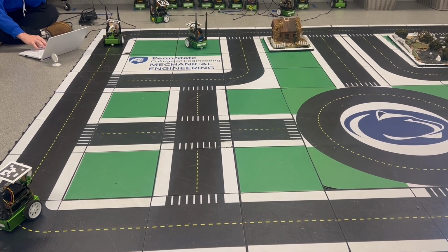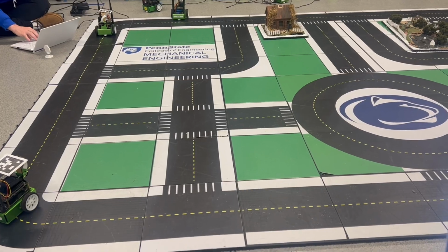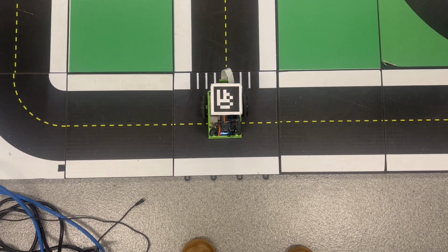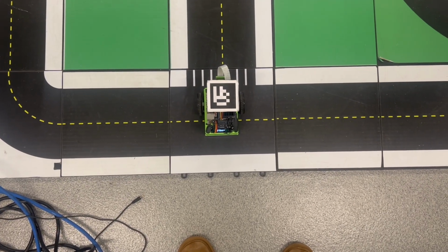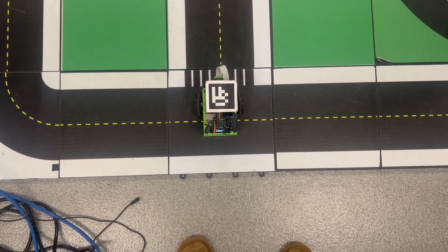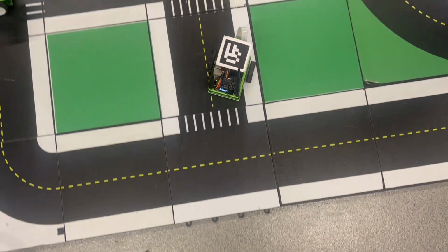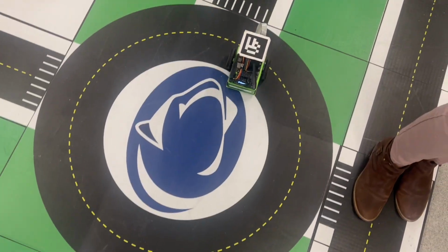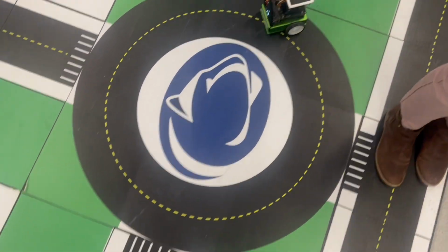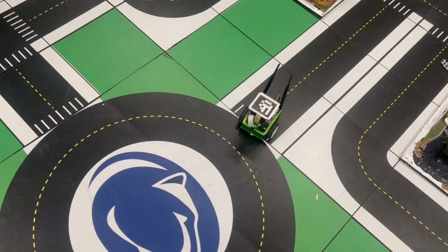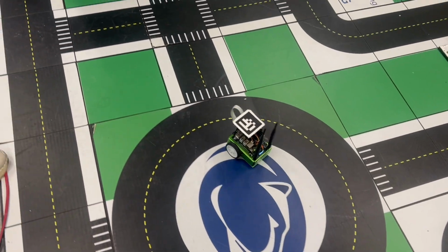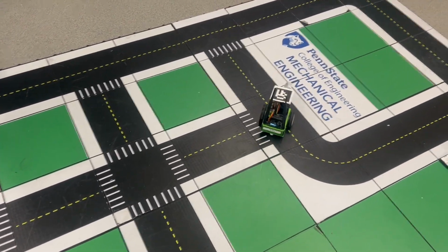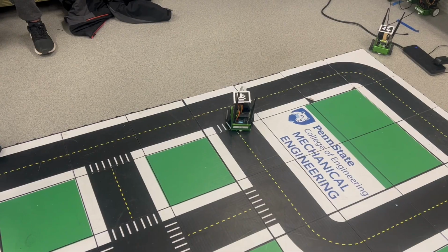To do this, we had to write code which first calculated the heading angles. Based on those heading angles, we determined the threshold for whether a right turn, left turn, or forward motion is required. We faced some setbacks at the start when the robot would move in an incorrect manner, causing the destination to be vastly different from what was predicted. After some time, we figured out that we had to change the motor speeds so it gives the robot an ample amount of time and distance to properly follow the planned path.